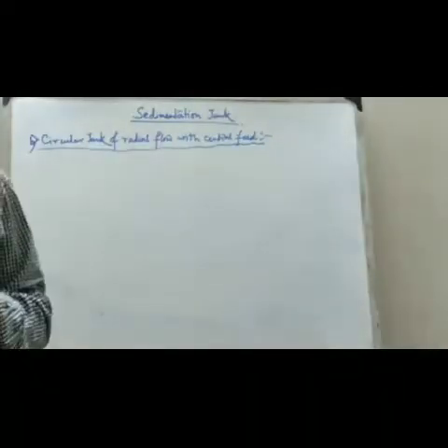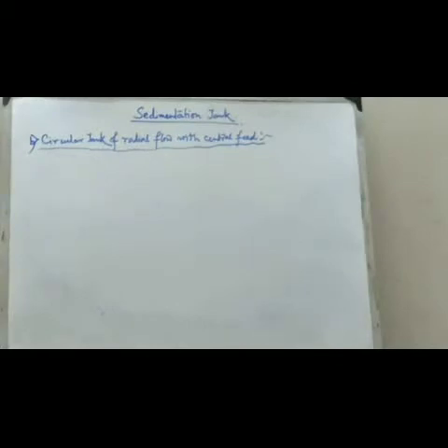This is another type of sedimentation tank, in which the water enters at the center of the tank into a circular well provided with multiple ports, from which it flows outwards equally in all directions, and thus flows horizontally and radially from the center towards the periphery of the circular tank.